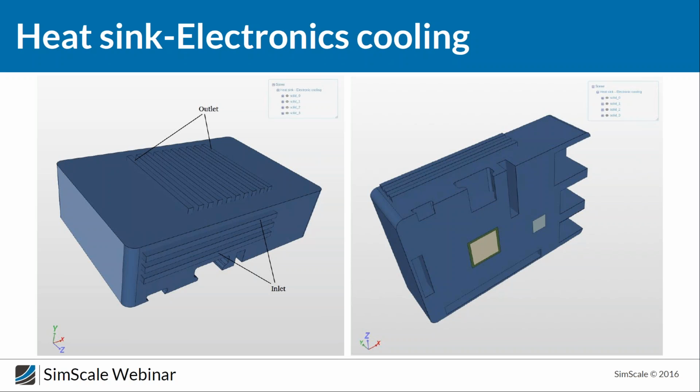If you look at the bottom of our geometry, we see two regions that have a different color. These are our two solid elements, our electronic chips that produce the heat. So we want to see how the flow of the air that we create through this inlet and outlet enhances the cooling of these two elements. As you will also see, on one of the chips we have installed a heat sink that should enhance the transfer of heat from the heat-producing element to the air.